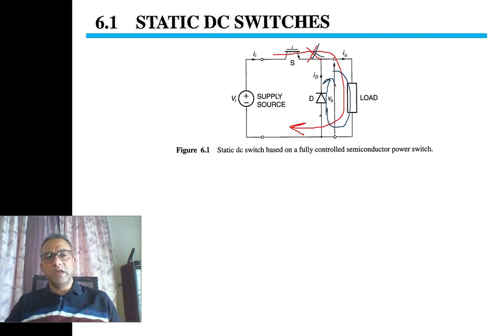So we have protected the DC-DC converter from sparking. Otherwise, the half L i square energy will produce a large voltage spike, or it will damage the power converter.